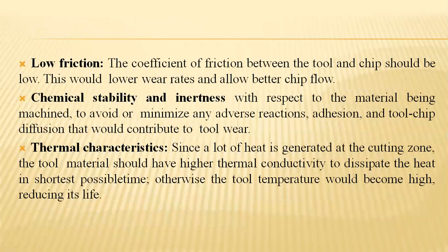The characteristic of low friction: the coefficient of friction between the tool and chip should be very low, as this lowers the wear rates and allows better chip flow.